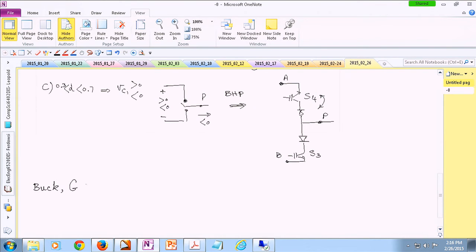We are talking about GVG, and it turned out to be, if you simplify that transfer function that I had earlier, D over a quadratic form. We expect that to happen because we have one inductor, one capacitor, so we would expect to see a second order behavior.